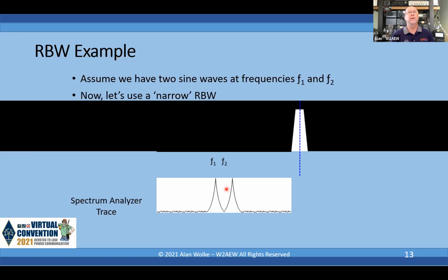and therefore to allow that filter to properly pass along the proper amplitude to the detector. Kind of the layman's way to think about this is picture yourself riding along the motorway. Okay, if you quickly glance around at all the cars surrounding you, it looks like you're all going the same speed. You're all kind of in a fixed position. You look around pretty quickly. But if you take the time to look at one car for a little bit longer, you can see how there's a slight difference. He's slightly pulling away from me, or I'm slightly catching up to him. But it takes that longer observation time to be able to resolve that small speed difference. The same thing happens electronically. If you want to resolve signals that are very closely spaced together, you have to have a longer observation time, a longer charge time to see that happen.